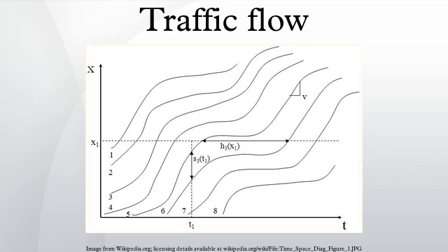Traffic stream properties. Traffic flow is generally constrained along a one-dimensional pathway. A time-space diagram provides a graphical depiction of the flow of vehicles along a pathway over time. Time is measured along the horizontal axis, and distance is measured along the vertical axis. Traffic flow in a time-space diagram is represented by the individual trajectory lines of individual vehicles. Vehicles following each other along a given travel lane will have parallel trajectories, and trajectories will cross when one vehicle passes another. Time-space diagrams are useful tools for displaying and analyzing the traffic flow characteristics of a given roadway segment